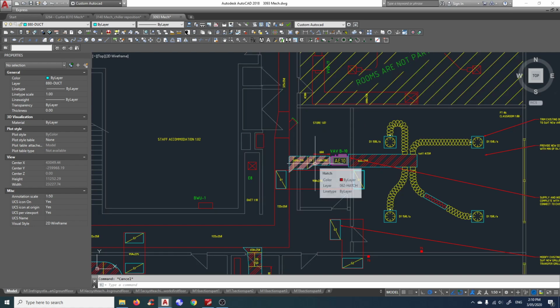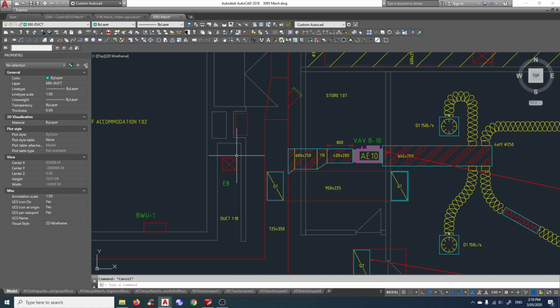For the construction drawing, the mechanical contractor has to go into the ceiling space and make sure this kind of system will fit. It's not going to hit a roof truss or anything. If they see a roof truss, they will probably make the duct shorter, or shift this, or make a bend. So that's what the mechanical contractor will do.